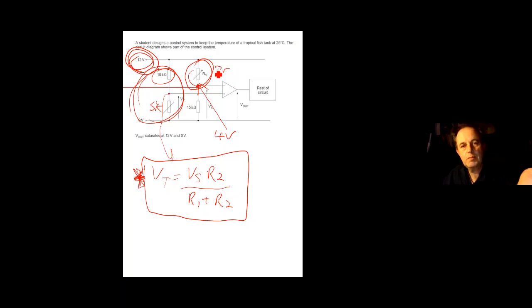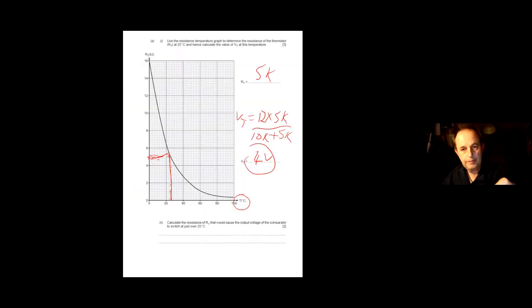So I've got to have twice the voltage on the top than on the bottom. The easy way to do that is, if it's going to be twice the voltage, it's going to be twice as big in terms of resistor. So if the 15k is on the bottom, twice as big would be 30k. There's the reasoning: it's 2 times the 15k for the top one.